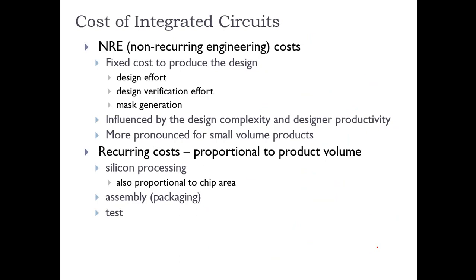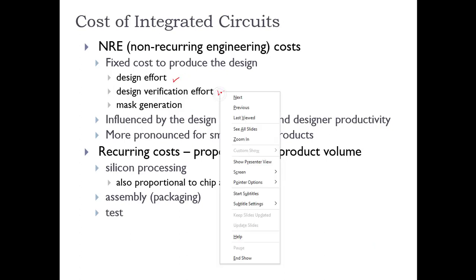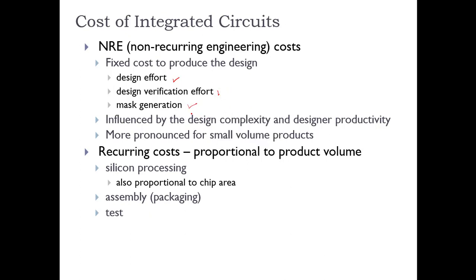So cost of integrated circuit, again this is explained a bit. So as I told you, the design effort of engineers, the design verification effort, I told you verification is a huge part. Then the mask generation, because your mask should be fault free.